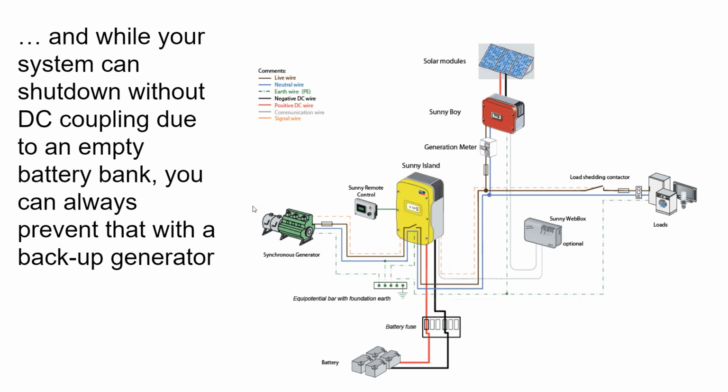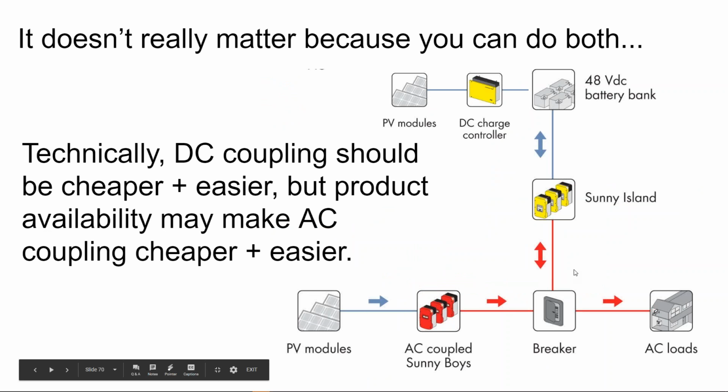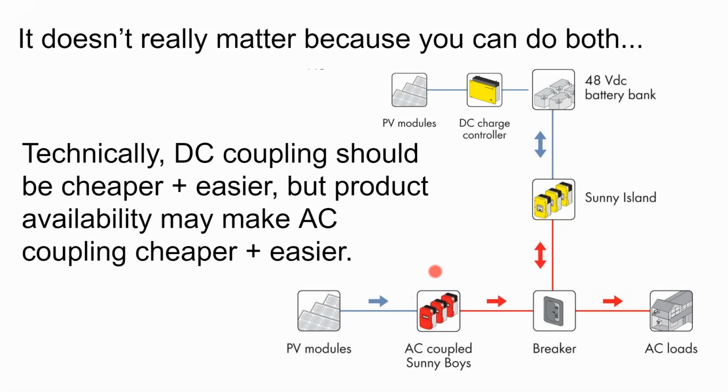Likewise with DC coupling, DC coupling is a little bit easier for off-grid because our inverters have protections in them that say that a basic dumb solar inverter without any batteries needs to see a grid signal in order for it to turn on and function.